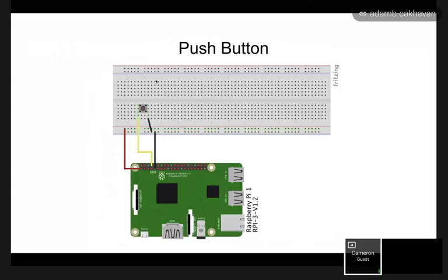So a breadboard is actually a proto board, stands for prototype board. And basically all these rails you see on the sides, just this red line that goes across, and this blue row that goes across, and vice versa on this other side, these are connected lengthwise. So this little hole in the top left corner is connected to all these other pins all the way up to this top right one right here, and vice versa for this bottom one. And these are used generally just to put in a power source into here and a ground source, and then it just makes hooking up wires really easy. But we're not going to have to worry about that today.